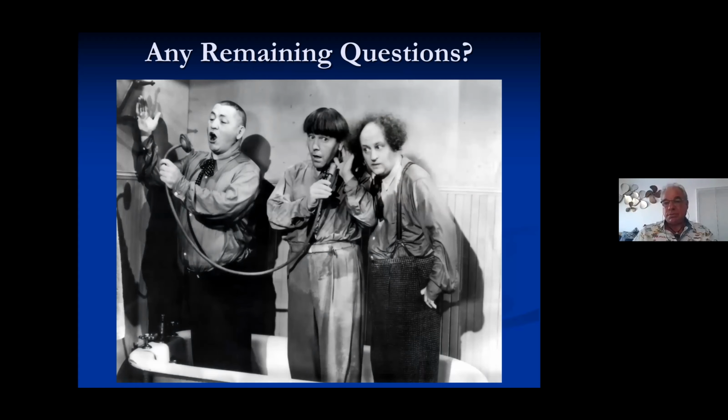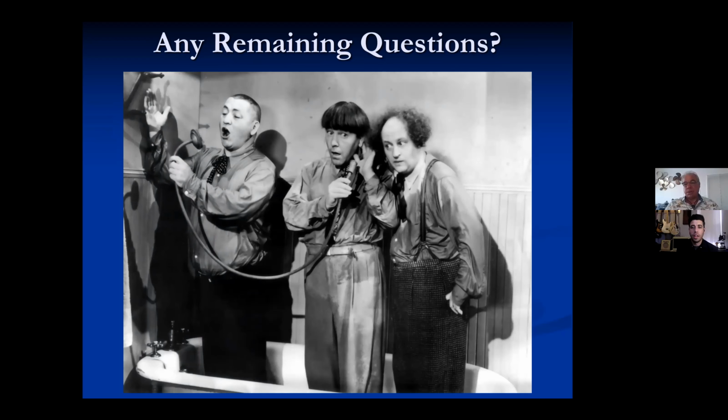Going back to the active inline amplifier. In cases where an antenna does have an amplifier built into it, for instance, active antennas as they're commonly referred to, what is your opinion on using that amplifier by default, or should you start off just with the passive gain that you would get out of, for instance, a directional paddle antenna, and then see if you would need to add any kind of amplification from there?